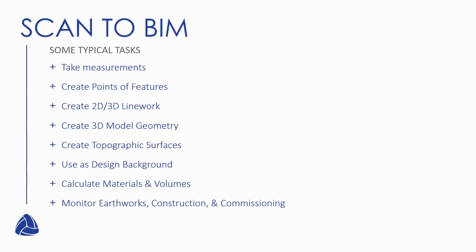So you can create a 2D site plan from a 3D point cloud, but you can also use it to extract 3D line work. And these would be your features, once again, such as your road center lines, paint markings, so that you can actually use the levels of these objects. You can use it to create 3D model geometry. So the 3D line work would then be put into use in the next step, which is Civil 3D, to actually create the model geometry itself.